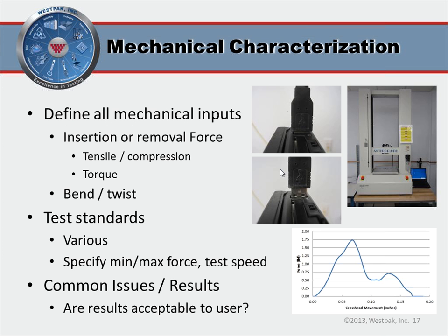And the plot there, you can see, is a force deflection plot of that being pulled out. The peak force it took to remove the USB cord was about 1.75 pounds of force. This is commonly done in pounds force or newtons, occasionally done in kilograms. So if you did this at the beginning of the test, then you life cycle tested that USB port 1,000 times and characterized it again, is it still within an acceptable level?